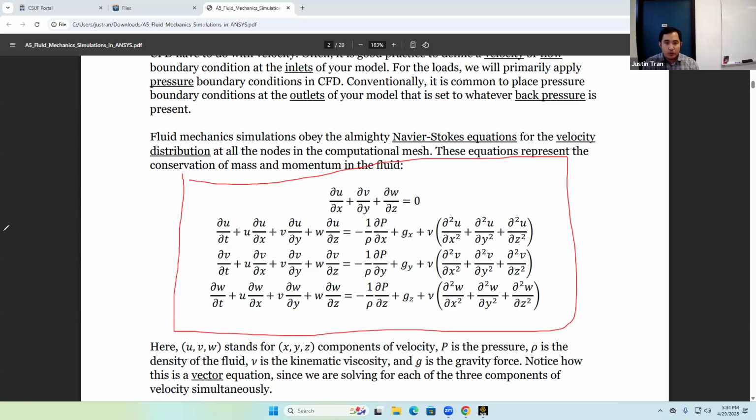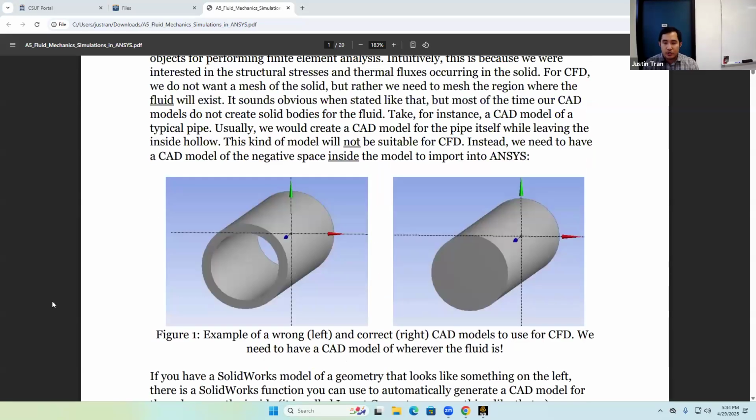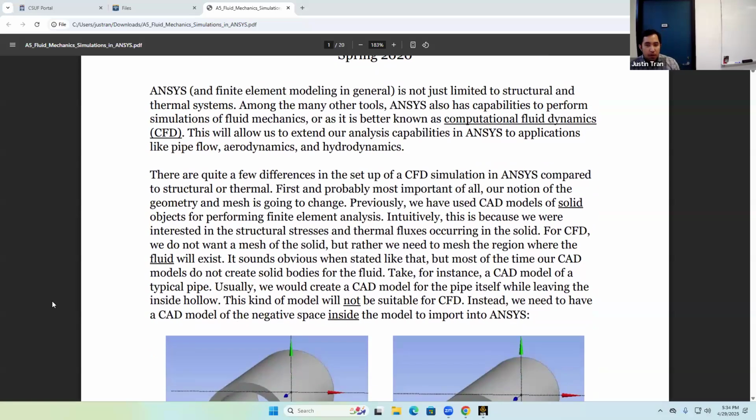Generally, the term used for computational simulations of fluid mechanics in practice, you've probably heard, is CFD. CFD stands for computational fluid dynamics. Finite elements for fluids does fall under the category of CFD. This is true CFD here, but the CFD that a lot of people use in industry typically uses a different method called finite volumes. It's similar to finite elements. It's just that the way it's formulated, the way the equations are made and the code is written, is slightly different.